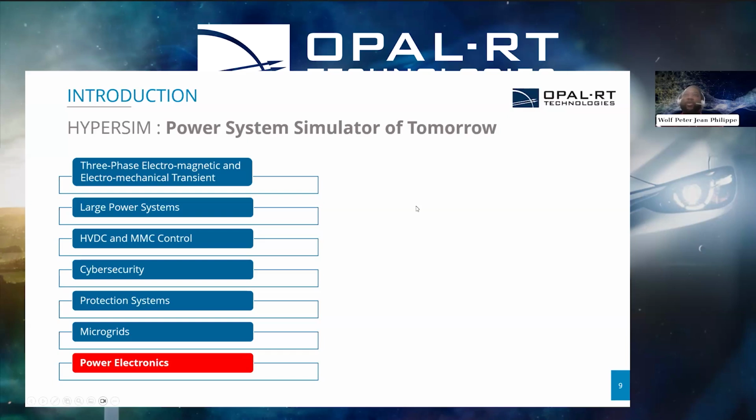That's why today we want to show some of the capability of HYPERSIM and some of what we can do on HYPERSIM. As some examples, we can simulate large power systems by doing decoupling. We can do HVDC and modular multi-level converter control. It can be used for cybersecurity. It can be used for protection systems and microgrids. And today, the main focus is going to be on power electronics related applications, where we're going to show how we can use HYPERSIM to do that.